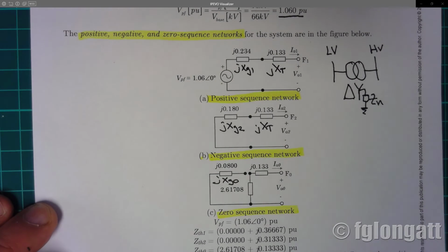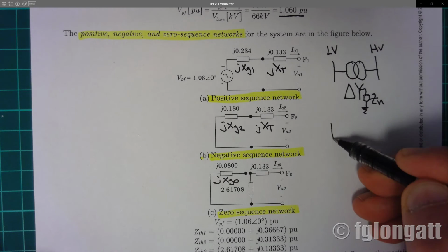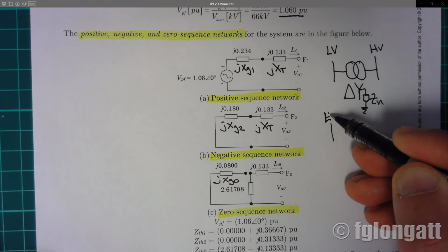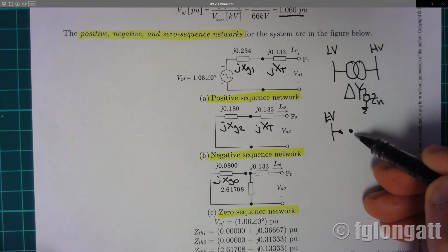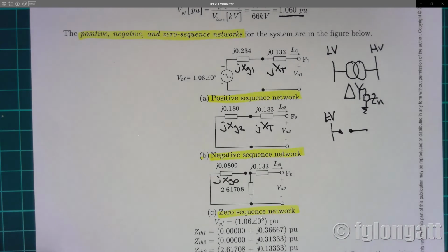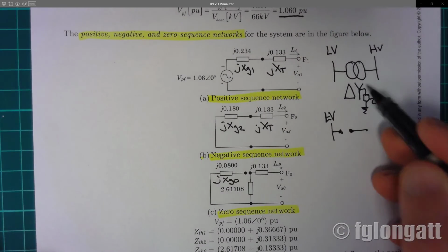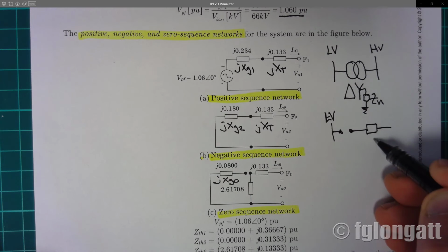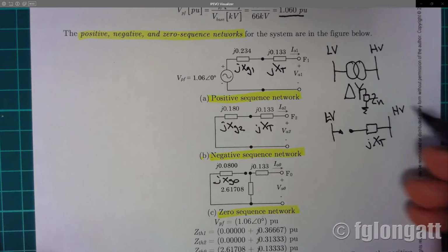If you remember from my classes, from my documents, when we have the delta connection, this is the low voltage side, yes? There is not possibility for zero sequence currents to move on the lines because the delta connection stops the zero sequence circulation. But on the star connection, we have here the reactance of the transformer, and this is the high voltage side.